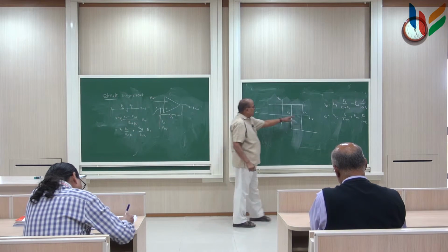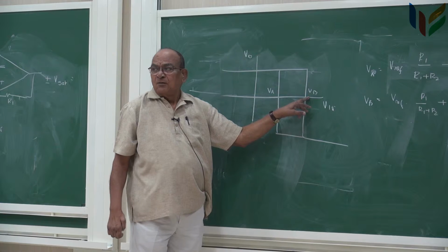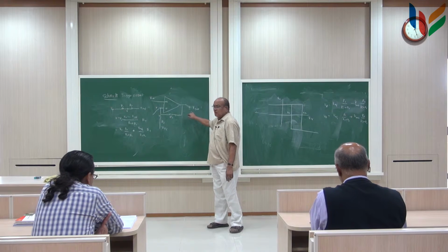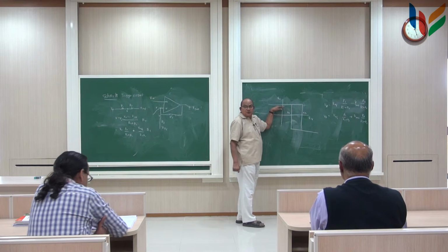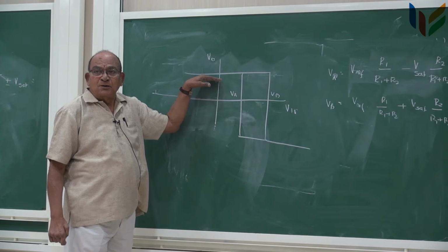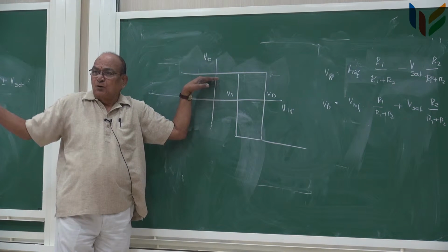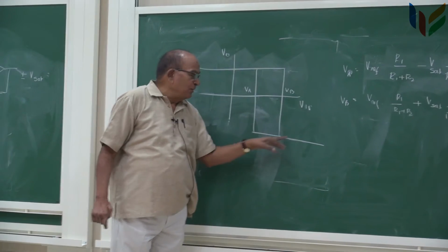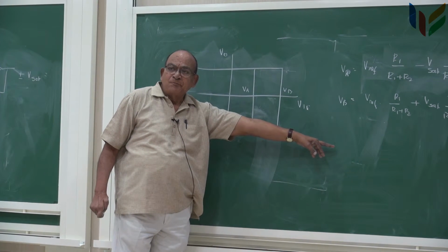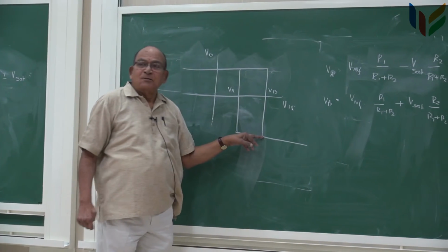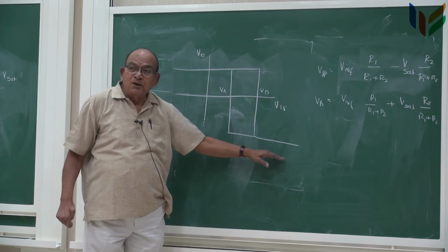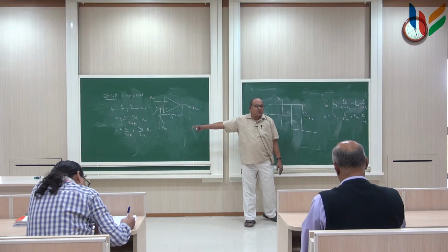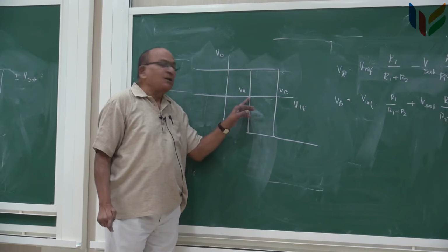As long as Vin is less than Vb, this fellow will sit at plus VCC, plus Vsat. Both input and output are now compatible. And then when the voltage goes beyond Vb, then it will go negative. But while coming back, this fellow is sitting at minus. So, the second equation will be valid with V0 equal to minus Vsat and the transition occurs at Va.